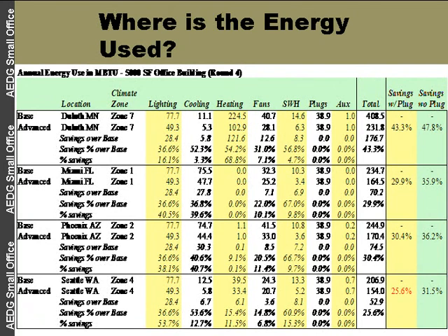And again, at the top, you can see that this was for a 5,000 square foot office building. But what's interesting in this slide is if you look at the savings in lighting, the first column there in yellow, you can see that the savings over the base, and the base again was the 1999 standard, was about 36.6%, which if you scan down between Duluth and Miami and Phoenix and Seattle, you'll note that it's always 36.6%. That was the nice thing, is that lighting is not something that is really climate zone specific.